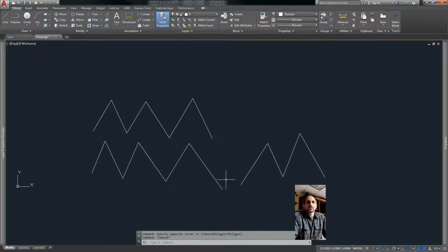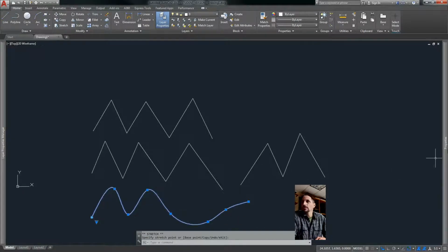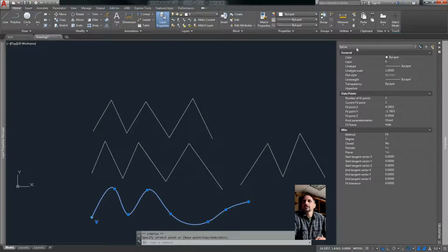Next we have the spline command. Up here in our drawing menu we have a couple of options for the spline command. The quick keys are SPL for spline. You'll notice this is more like a fit curve. If I highlight this, you'll notice that the grips along this length can be adjusted, and you can adjust your spline in different positions.